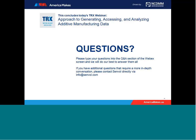So let's jump back into another couple of questions that go earlier in your presentation. How do you decide what input parameters to use for the builds for the Senvol Index? For example, machine parameters, scan speed, build position, support structure, et cetera. Our philosophy is to what I'll call over-track. We track for Senvol Index data, and I would recommend anyone generating pedigree data adopt the same mentality, which is that we track any parameter that might theoretically impact results.